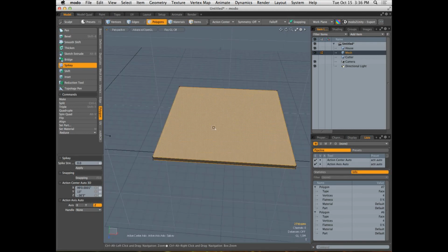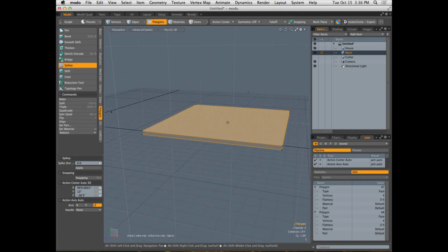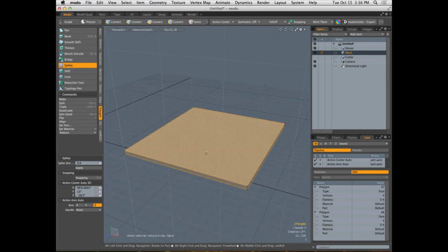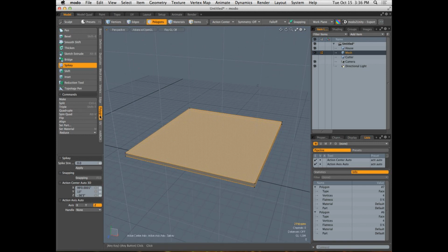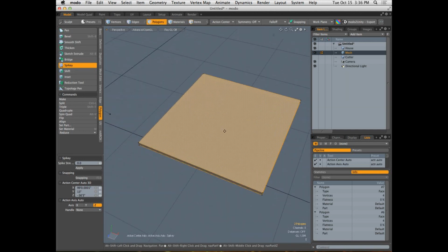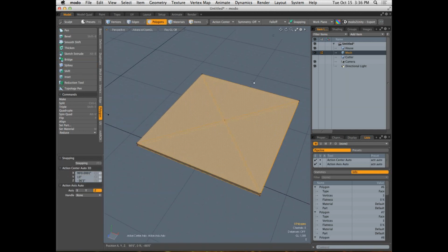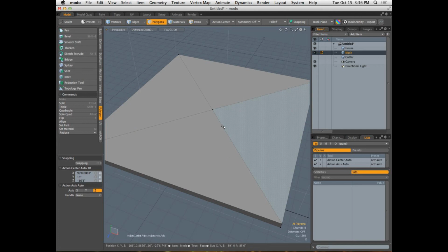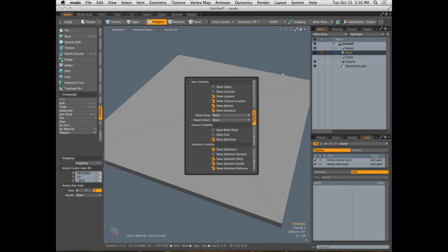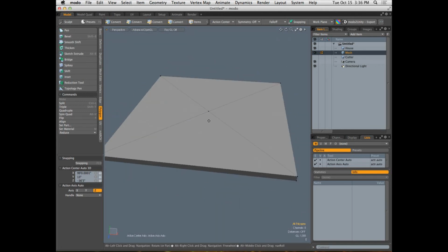So here I am. I have that top polygon selected, that bottom polygon selected, and I've gone into my polygon tools. Okay, just the top and bottom, not the sides. Correct. Okay. And the Spiky tool is automatically going to slice up our mesh, and it's going to give us that. And that's under deform or? It's under polygons. Polygon. Spiky.